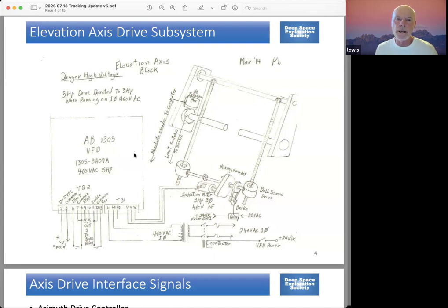And it also, in combination with that specific frequency, selects a voltage that's appropriate for that frequency. So that basically sets the rate of the motor. Another difference is in the elevation, there's no feedback mechanism from the motor back into the motor controller to tell it that it can sense the rate. I think it basically just depends on the frequency, basically setting the rate. It's kind of a blind, no feedback approach.